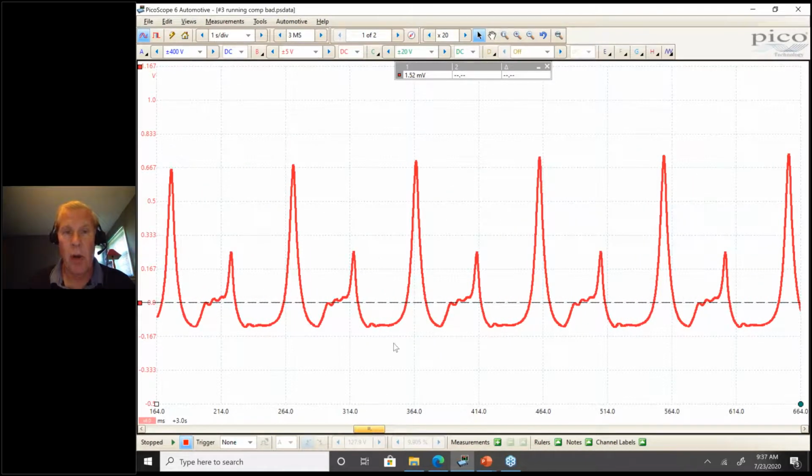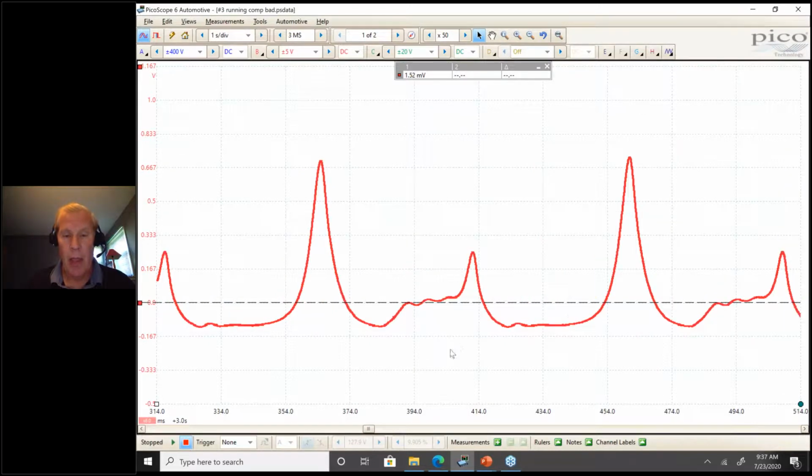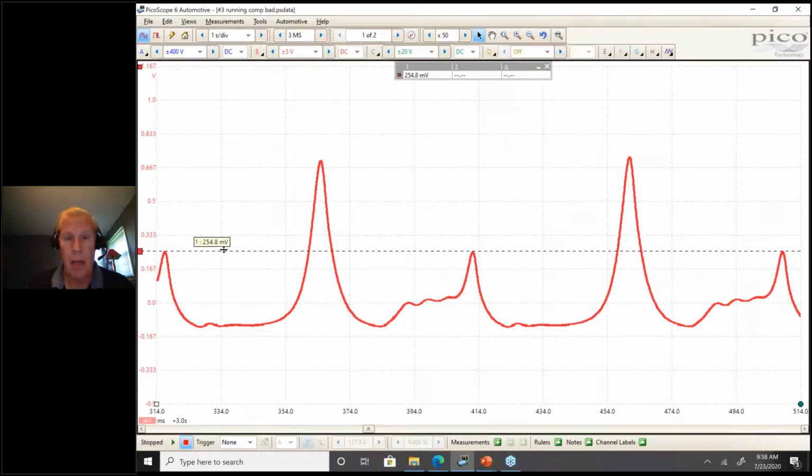So I'm going to zoom in some more horizontally. And you can see we have an EVO. We hit 0 PSI. We stayed there for a while, which probably suggests that we don't have a restricted catalytic converter. And of course, if it's a single cylinder event, it probably wouldn't be a catalytic converter anyway. And then we have a pressure pulse, and this pressure pulse is hitting about 25 PSI. So it's a pretty significant pressure pulse.